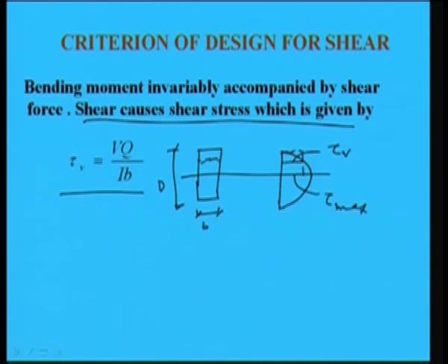That means with equivalent area, this will be tau VA. So, this is called tau VA, and tau max will develop at the neutral axis, means at the middle, at the CG or somewhere else, means at the middle basically in this case, and it will be 0 at the end, right. So, in this way you can find out, and tau V can be expressed from this equation.